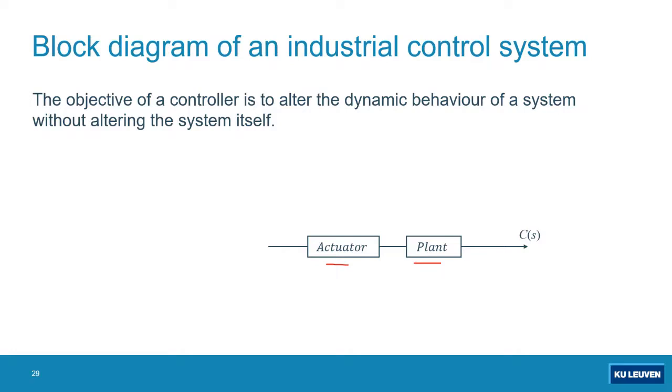Let's say your DC motor apparently exhibits a very large steady state error when you want to run the DC motor at, let's say, 1000 RPM, but apparently after you run it and then you let it run until it reaches the steady state condition, your DC motor only runs at 950 RPM. So there is a steady state error of 50 RPM.